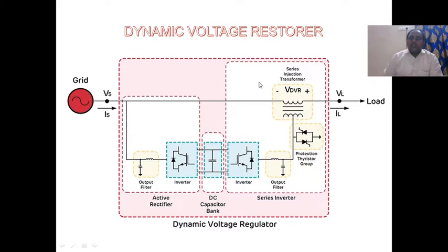Normally the previous components, that is shunt capacitors or shunt reactors, are all impedance changing devices. They change the inductive reactance or capacitive reactance by adding capacitors or inductors. But the dynamic voltage restorer operation is different. This DVR directly supplies the voltage the distribution line needs; the voltage drop will be compensated by using DVRs.